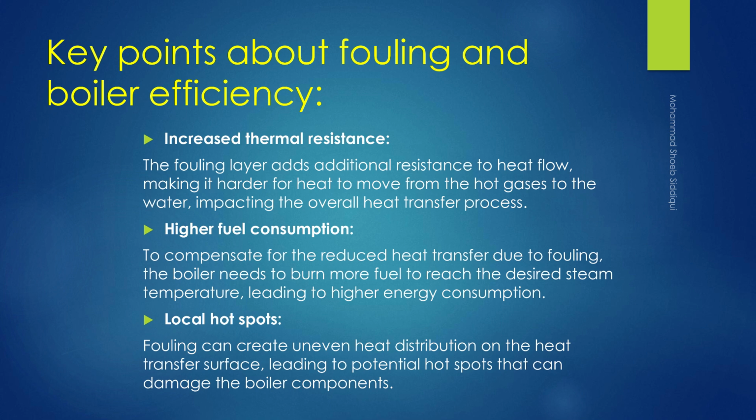Higher fuel consumption. To compensate for the reduced heat transfer due to fouling, the boiler needs to burn more fuel to reach the desired steam temperature, leading to higher energy consumption. Local hot spots. Fouling can create uneven heat distribution on the heat transfer surface, leading to potential hot spots that can damage the boiler components.